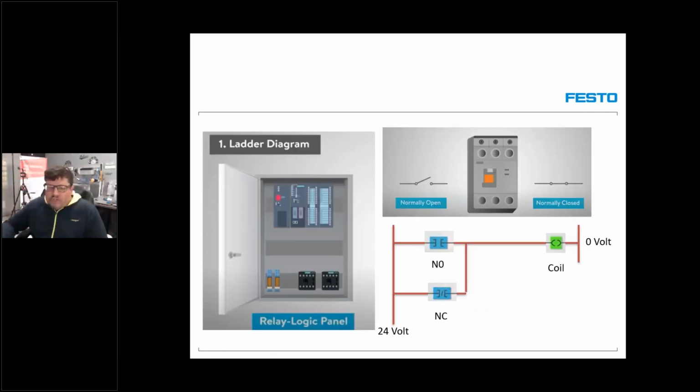Right, it's important to start off by giving you a little background and insight about the ladder diagram. The ladder diagram comes from the old relay logic panels, where they used relays for control circuits. All right, within ladder, we normally use normally open contacts, and we also use normally closed contacts. A normally open contact needs to be represented by a symbol within the ladder diagram language.